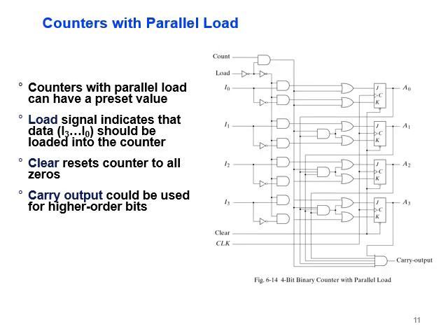Now, when we want to also use the property of a counter with parallel load, as you can see here, parallel load means we have load inputs I0, I1 into I3. Okay, what we will do here, don't forget, we always try to see sum of products. So the OR gate is here, but the input will be through AND. Now, load will come as input to each AND gate here, this one and the other ones, with input.